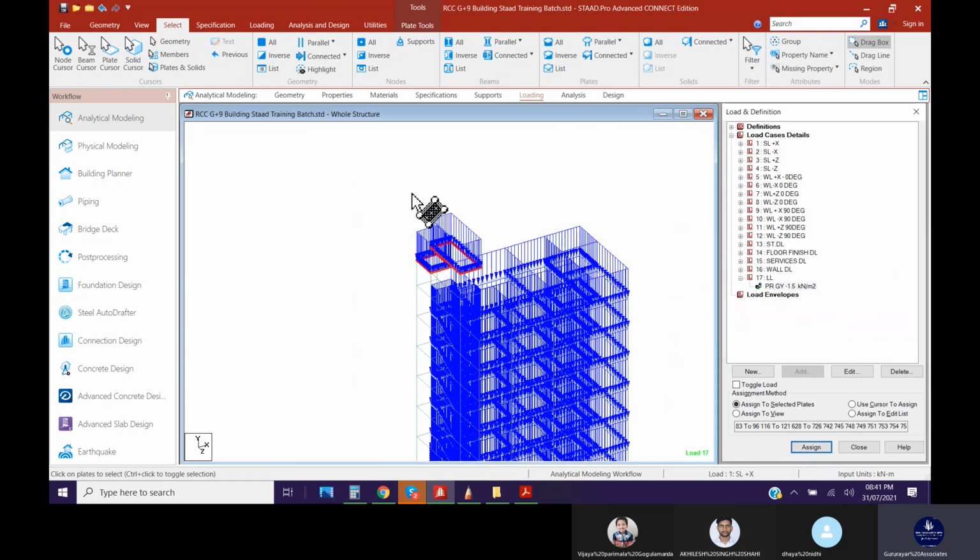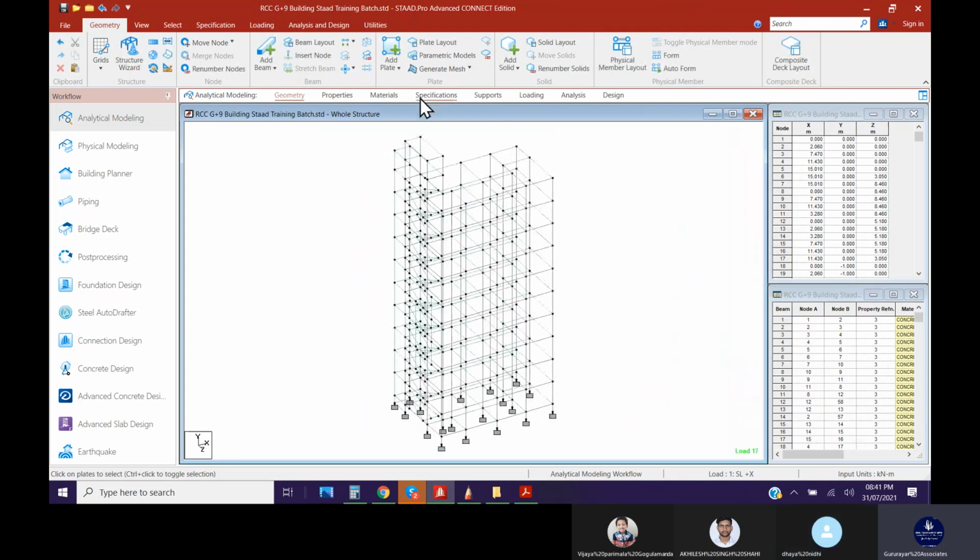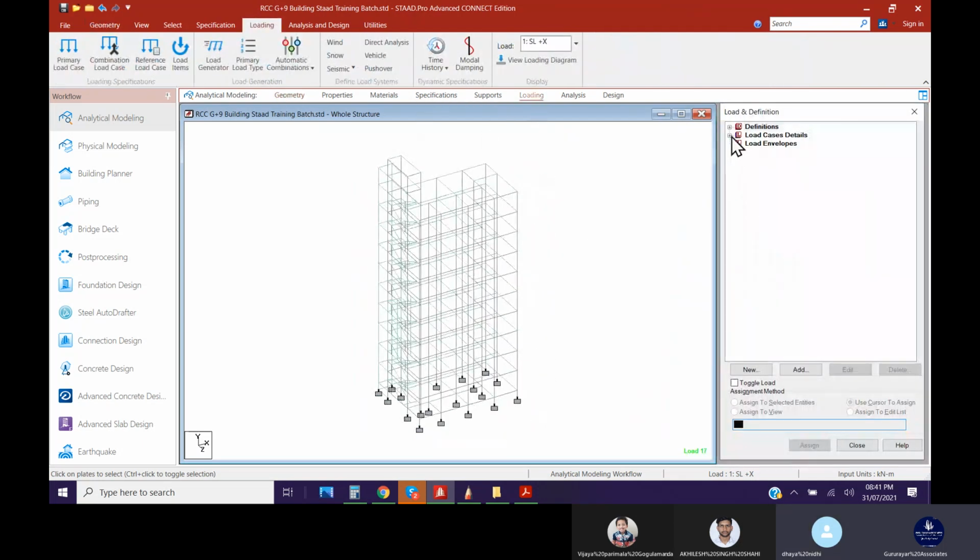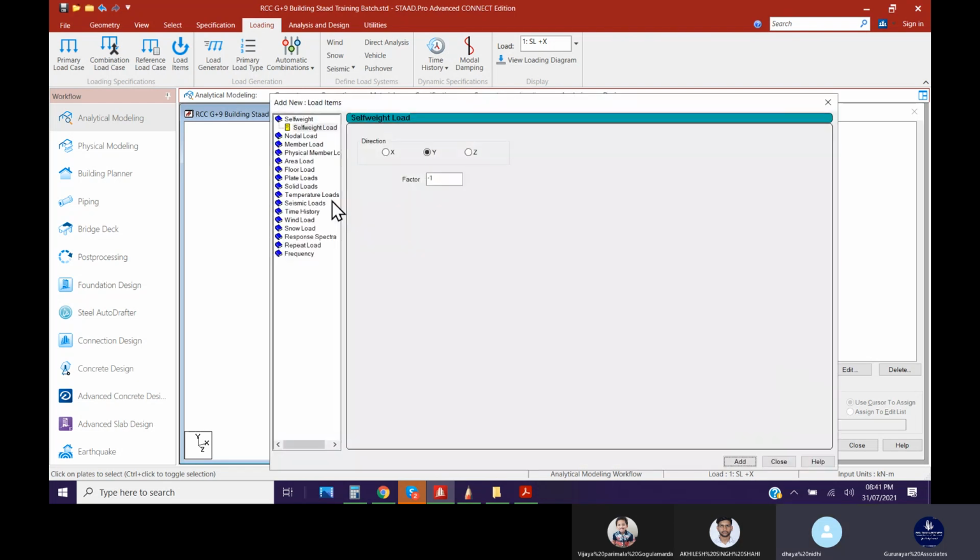Live load is also there because maintenance people will go and work. But for the bottom level loading, for the water tank, inside the water tank, water pressure will be more. That water pressure we have to give as a live load, or you can add a separate load for water pressure. Add one more load, primary.